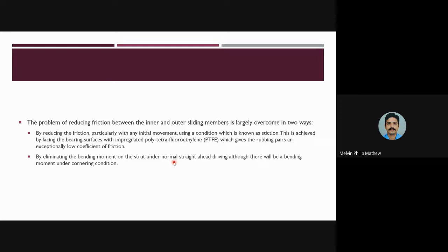So when this happens, the camber gain that we have intended to use will not be efficient, especially during cornering. In cornering, I told you there is a slip angle, and once it exceeds the slip angle, the body rolls. This rolling capability is then further reduced by increasing the camber.